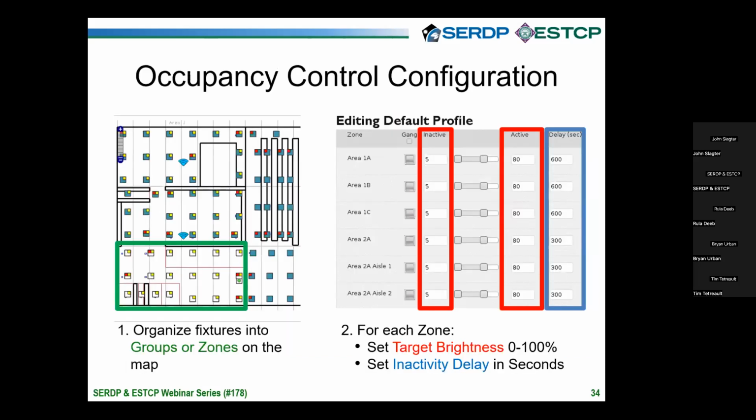Separate from that, we enabled occupancy controls. And again, in conventional systems where you use hardwired controls, you're very limited in what you can do. You basically tie circuits together and put a sensor on the ceiling and hope for the best. And I think many people have been in a room where the lights turn off and you're waving your arms around trying to catch the attention of a sensor that's in the corner of a room, and it doesn't do a good job. So that can be very frustrating.